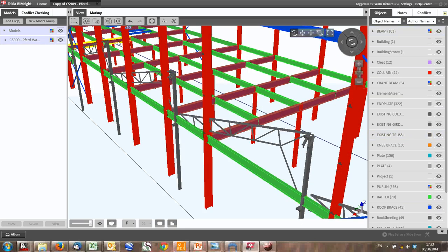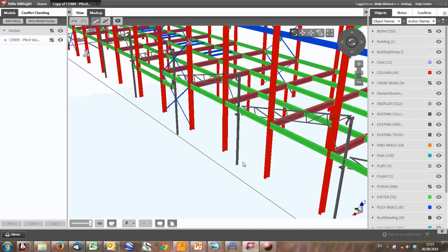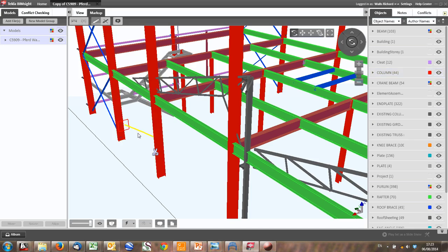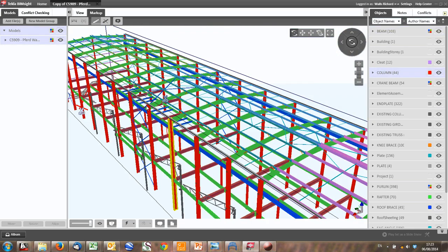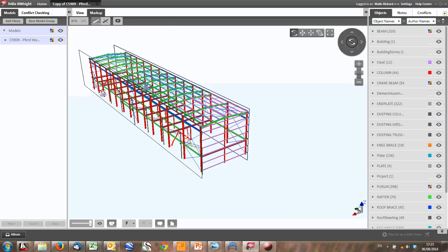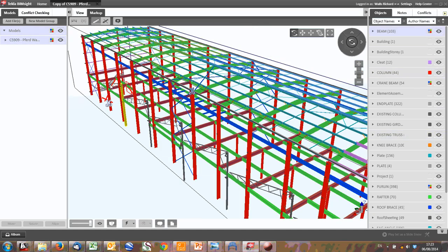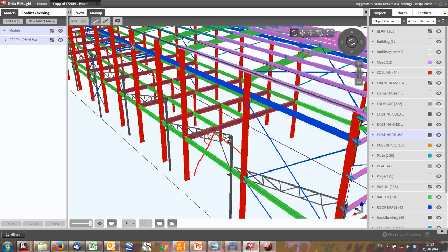So, if we now add a bit of bracing on this side, I'm going to add some here, and bracing there, K-brace, that will allow people to drive through, or we could add in a cross brace. And we add in a K-brace here. K-brace. There we go. You can actually then span the load from there to there, and then the lateral load can be taken by this floor, and then taken all the way down to the end bay, and you can just design that brace to carry the load.